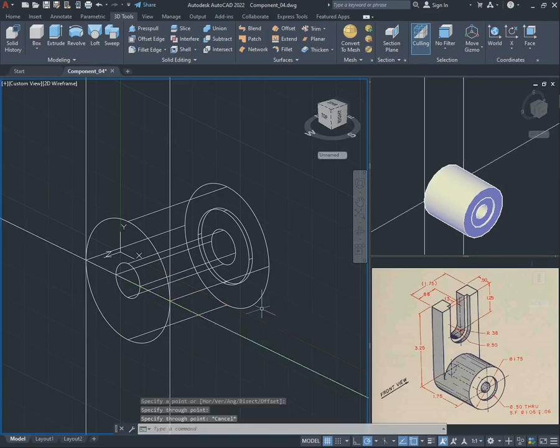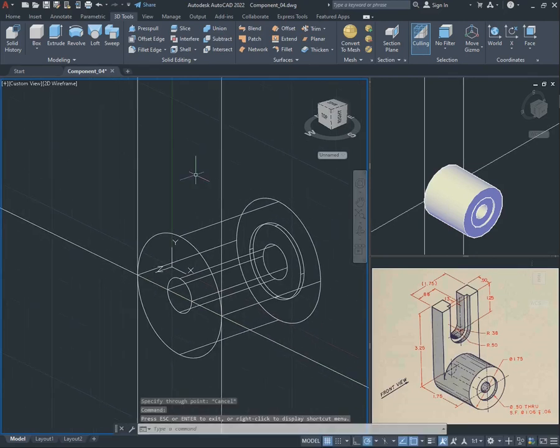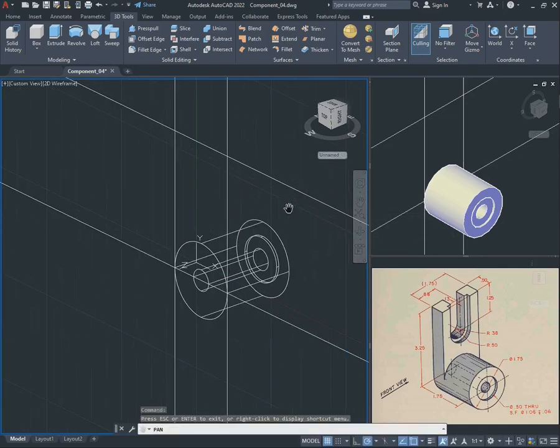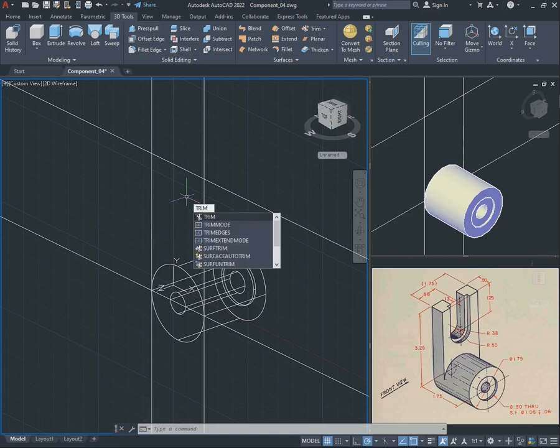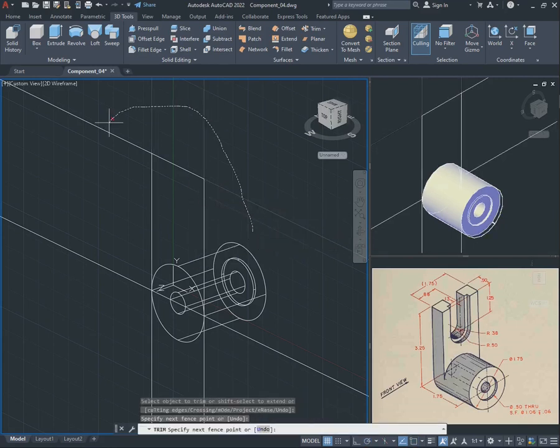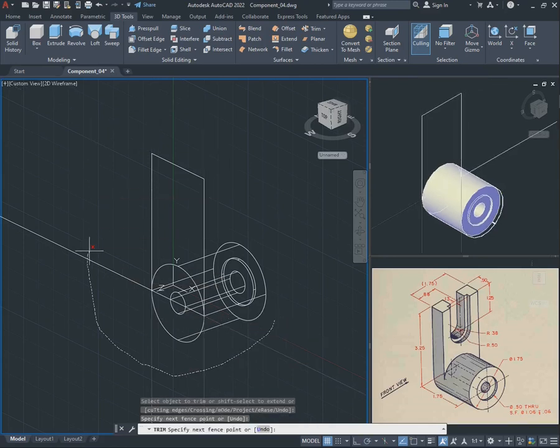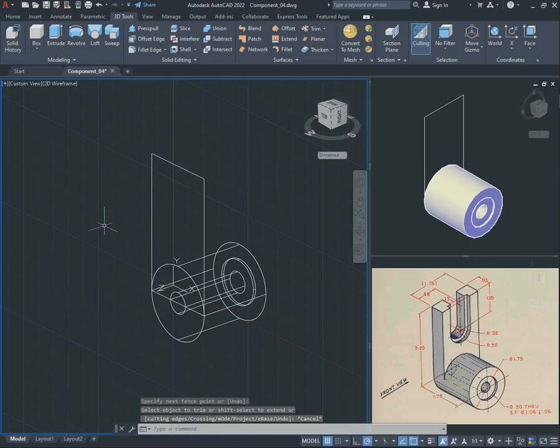There you go. Now that we have that, I wanted to use the offset to offset the horizontal X line with the distance of 3.25 units. So there you go. We're going to zoom out. So there, and then we will have an X line. I know we don't need an X line yet, so I think we can trim out this X line, or the excess line that we have here. So trim all those things.